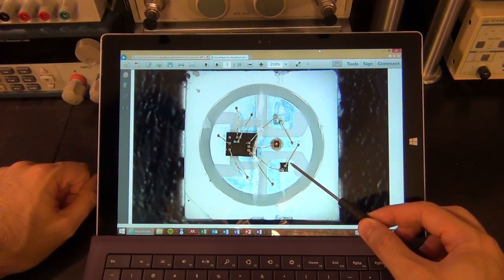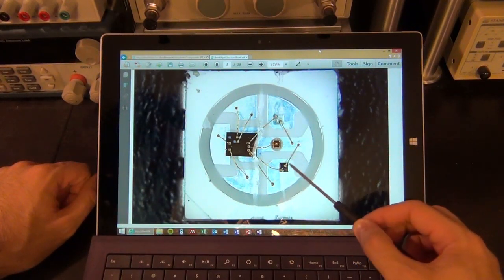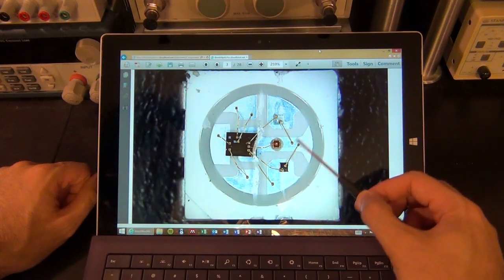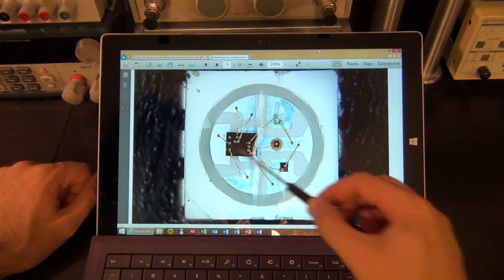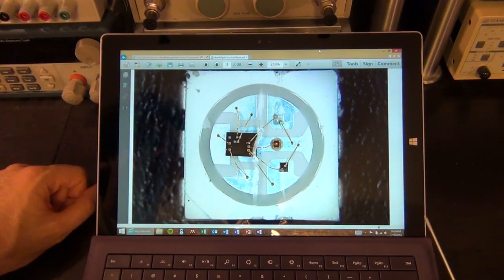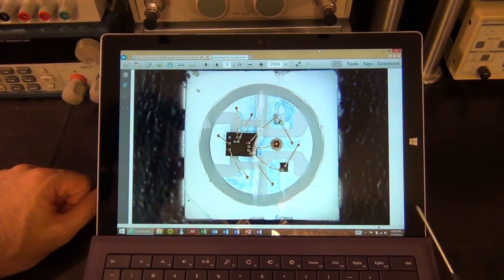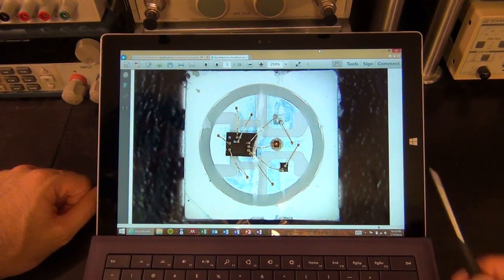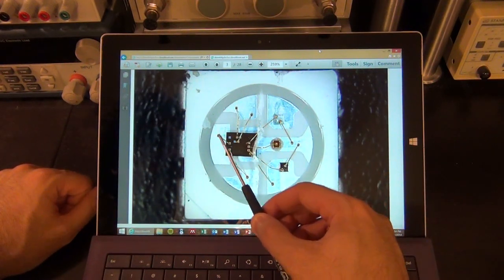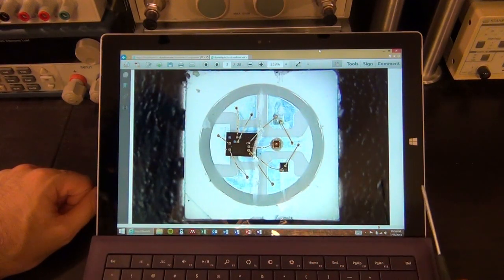The only thing that's interesting to note here is that each of these LEDs is sitting on top of its own little metal connection, and they're sharing the connection in the middle using these wire bonds. And at the left here, you can see a piece of semiconductor IC, most likely a very old CMOS technology, maybe a 0.18 or a 0.35. I have to look more in detail, but it doesn't need to be very fancy because it's a reasonably low speed technology. Anyhow, it has to support 5 volts. You can see a whole bunch of connections to it. Probably there's a data in and a data out. One of these 2 pins is D in and D out, and the rest is VDDs and grounds.